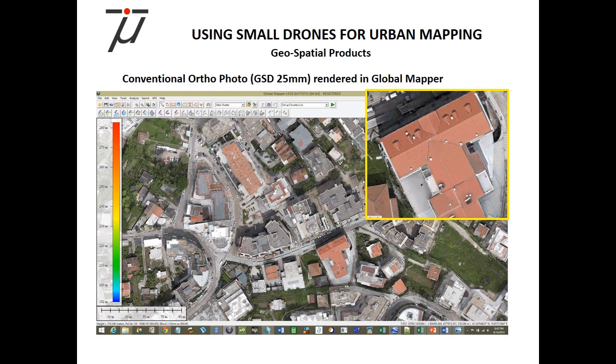And then, of course, the product that they were all after was an orthophoto. So they weren't really after all of this byproduct stuff. But mapping these days is a product of modeling. It's just one specific side product of a 3D model, because you can't get to the map unless you do the 3D modeling. So here we have an orthophoto. The GSD is 2.5 centimeters, 1 inch, for those of you who are more comfortable with that.